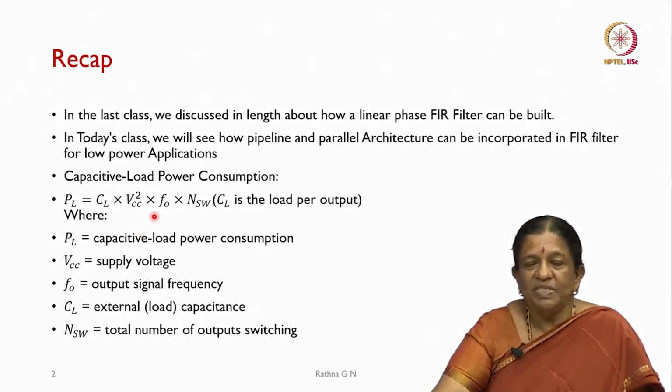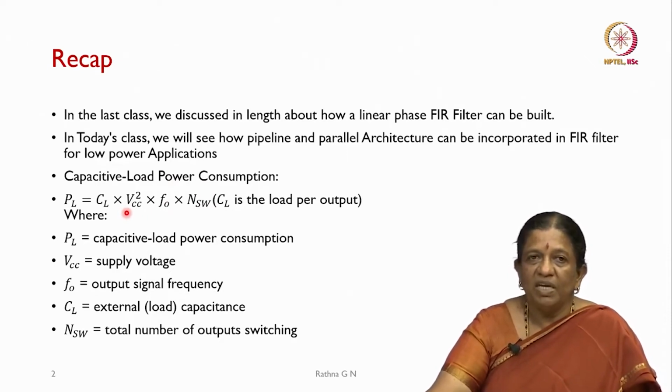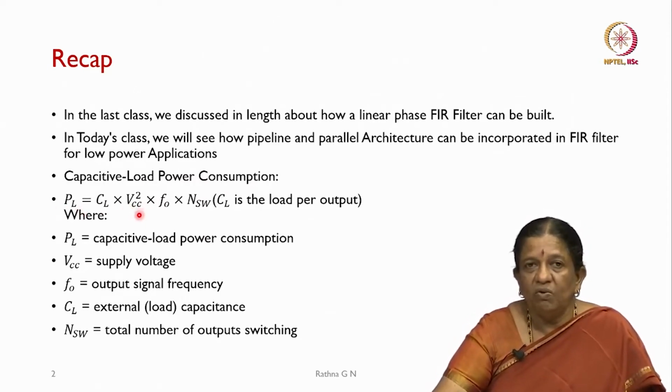We have seen that we can use architecture for speeding up our computation using pipeline and parallel processing. So the frequency is going to be increased, but in this case we will see how we can reduce our power consumption by reducing our operating voltage.